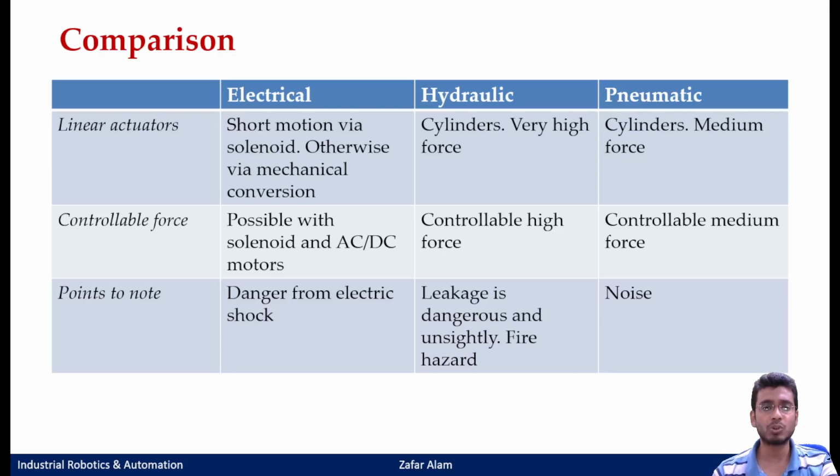If you talk about the controllable force, for electrical it is possible for all. In the case of a solenoid it is possible, and for motors also. In a solenoid, how will you control it? You can control it by the amount of current that you are supplying. Accordingly your magnetization or field is controlled, and hence the magnetization of the inner core depends upon the current that you are supplying to it. Hydraulic is also controllable, but the forces are higher, and in the case of pneumatic it is still controllable but with a medium force.